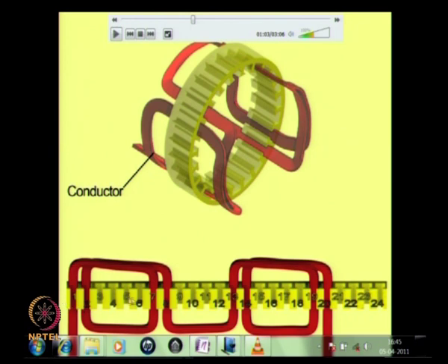So, one pole, if it is going to influence the section from here to here, then R phase occupies 2 slots out of this. The next pole influence starts here and therefore R phase occupies 2 slots again here. Again the third pole and the fourth pole. So, 2 slots per pole, and this is how the winding in one phase is going to look.